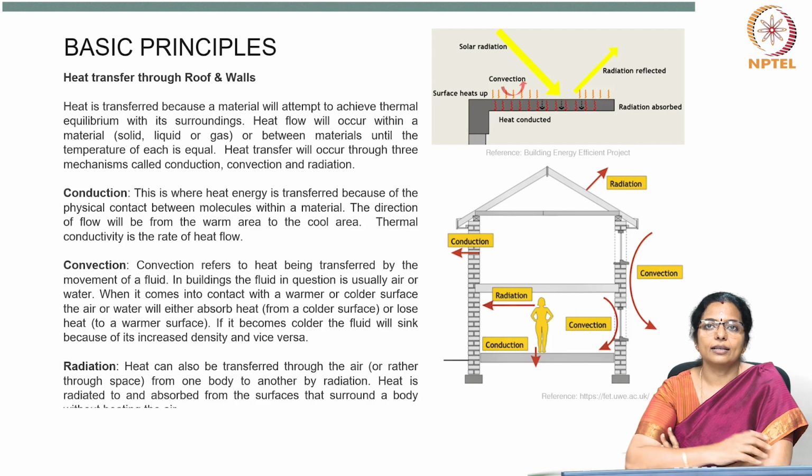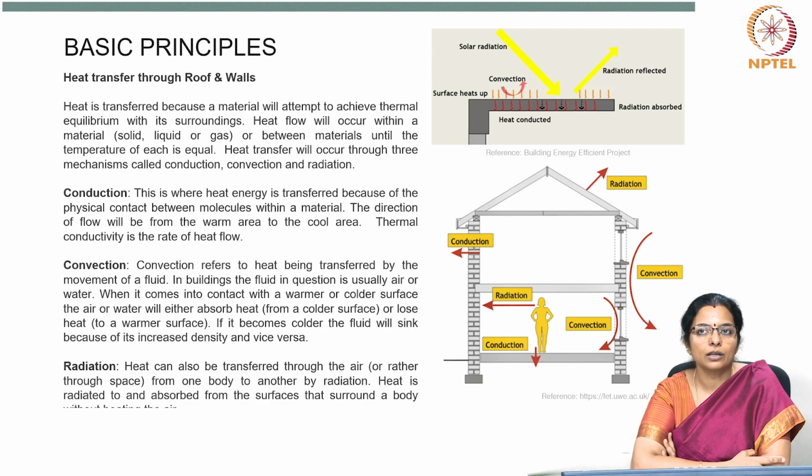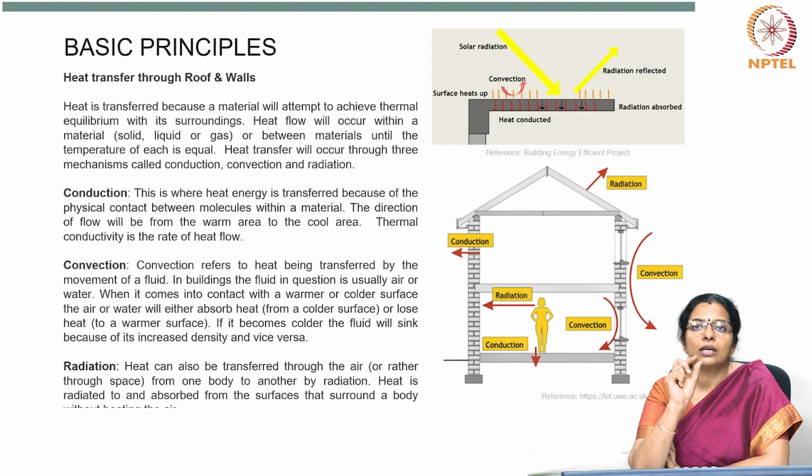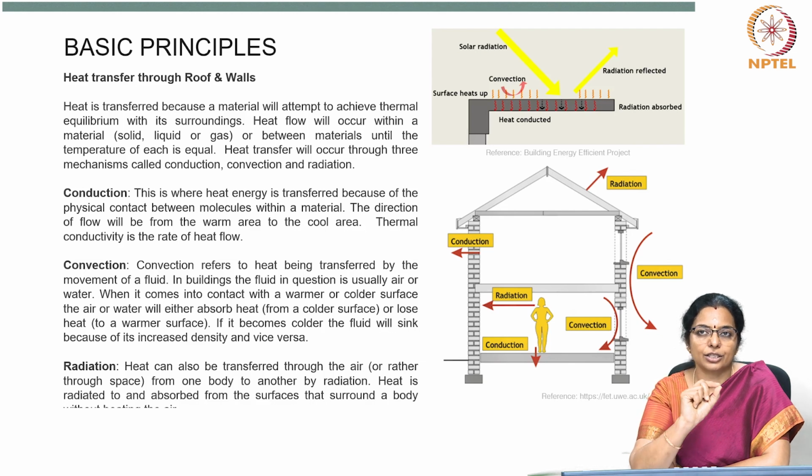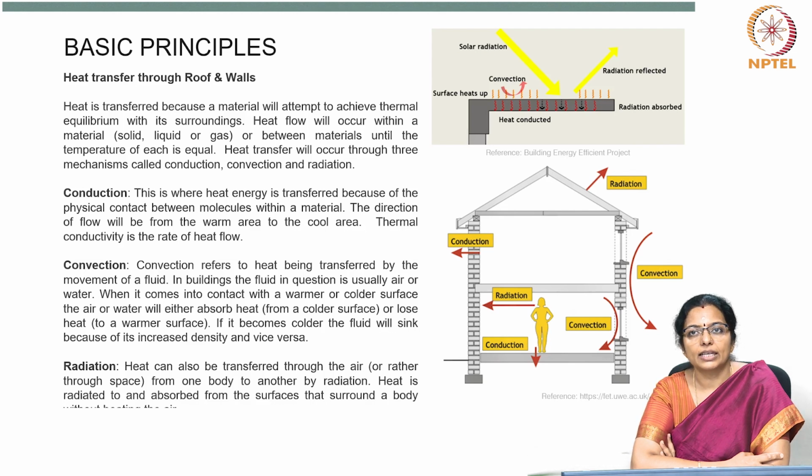This is where heat energy is transferred because of the physical contact between molecules within a material or between materials that are touching each other. Physical contact is necessary in conduction. The direction of flow will be from the warm area to the cool area. Thermal conductivity is the rate of heat flow, that is, a factor which is determined by the ability of the molecules to conduct heat. The human body is sensitive to the heat flow rather than to temperature.